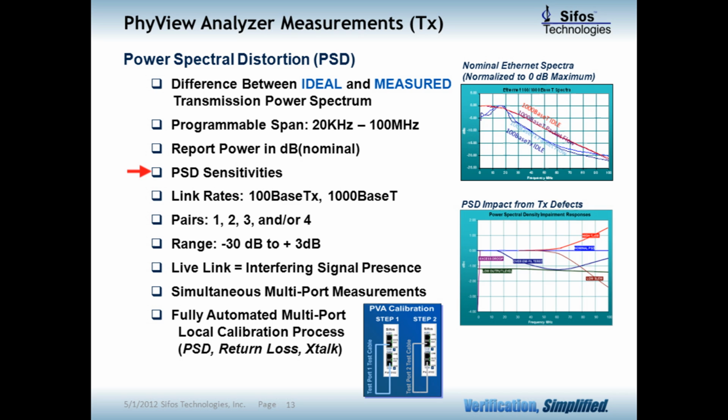Different output level, or peak-to-peak voltage, affects power measured in the low megahertz regions. Slew rate, or rise-fall time, affects power at frequencies above 60 megahertz. Droop, or baseline wander, affects power at very low frequencies below 200 kilohertz. Defects in magnetics and connectors can result in power excursions in any frequency band depending on the nature of the defect.